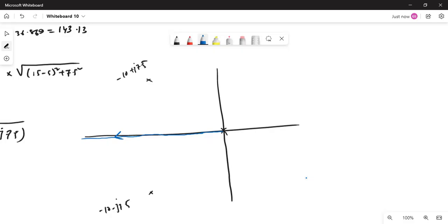And for the other two, how many infinite lines should there be? There should be 3 infinite lines because we have 3 poles only, there is no zero. So based on that, we can find our sigma A. Sigma A is the summation of the poles minus the summation of the zeros. So first pole at 0, then the second at minus 10, then minus 10, divided by poles minus zeros. So 3 poles, no zero. So ultimately it will give you around minus 6.67.